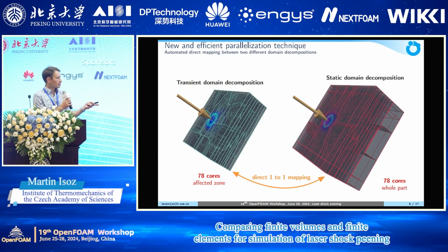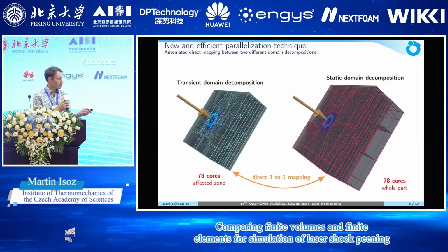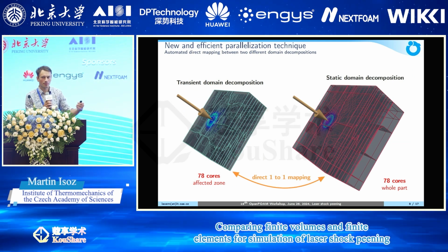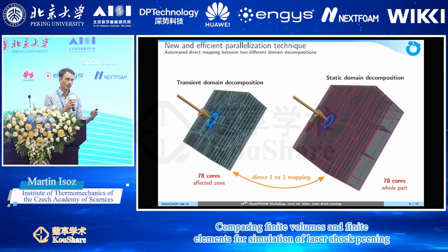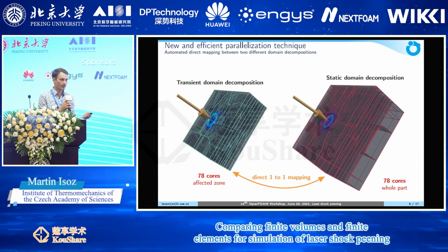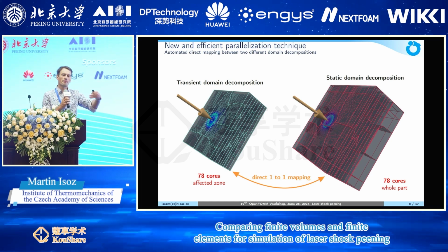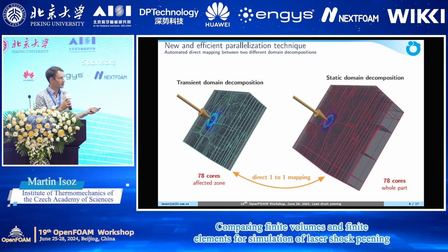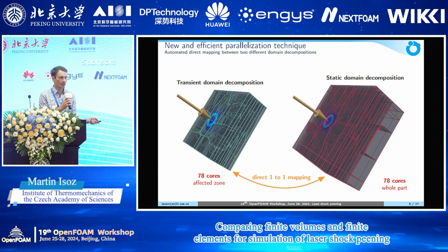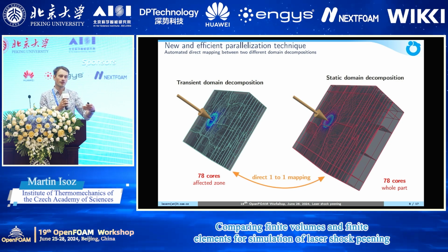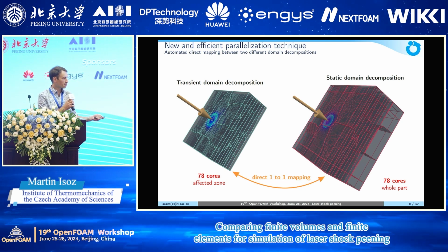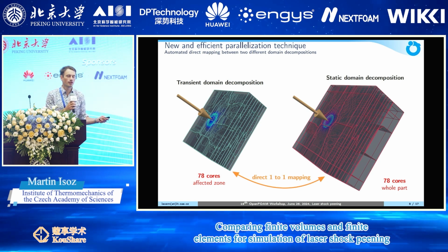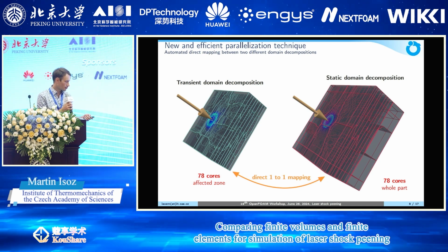We did a little bit of programming ourselves, caused by the fact that the dynamic wave propagation happens only very close to the material surface, but the relaxation and the residual stresses reach much deeper into the material. Because of that, we need two domains, one that represents only the material surface, the other that represents the full material that we need to simulate. And we implemented a way to directly map data between the meshes on the fly. So that was a little bit of technical programming.